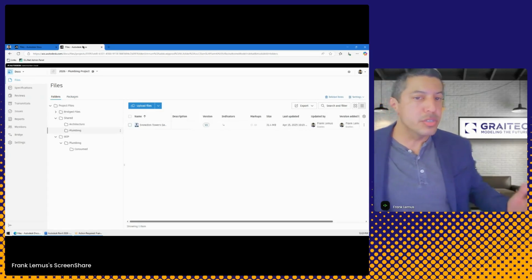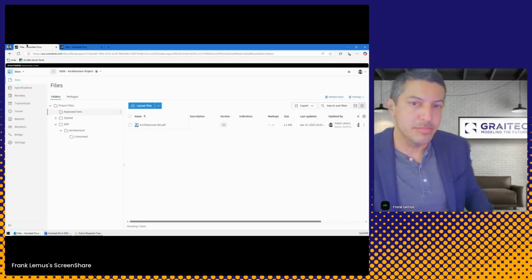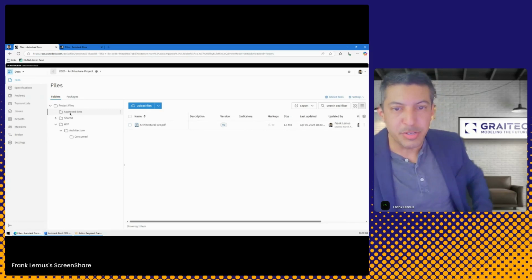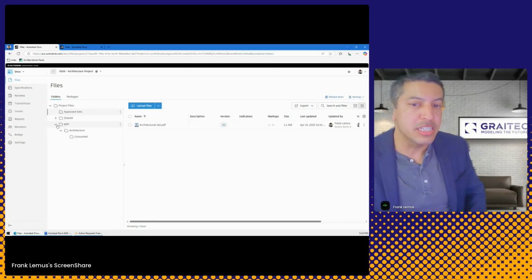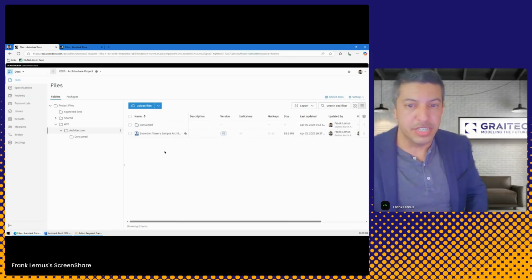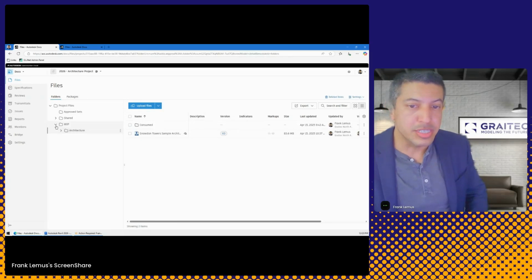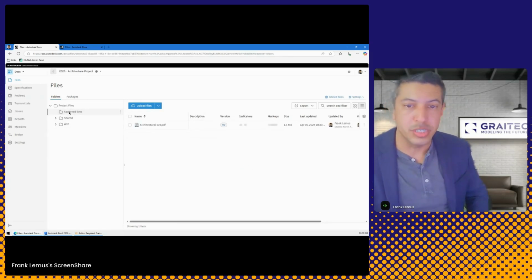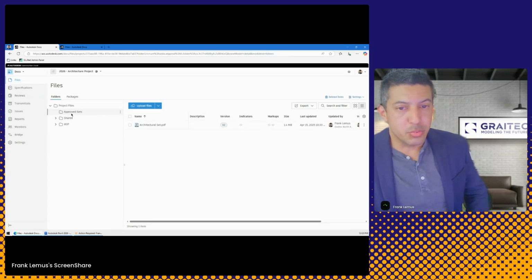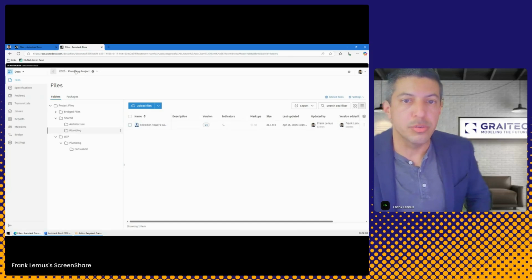And the idea is that I want to transfer anything that I put under this folder over to the other side, but I don't want to use Design Collaboration's package feature, because normally the Design Collaboration's package feature is going to be handling RVT files. Now, of course, you can attach non-RVT files to those packages, and I'm sure you all have tried that at some point, but Autodesk has given us the ability to do the following, so I want to show us this as well. And the way that this works is I'm just going to tell the ACC environment from the architecture project side, I want to share the approved sets folder, which includes this PDF, over to plumbing.